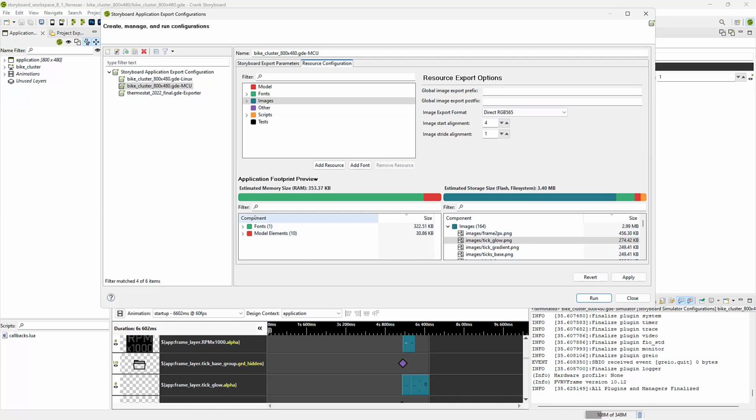Now you'll notice a difference in the sizes. At design time, we've pre-processed that file. We've inflated it. We've laid it out in a way that is compatible with the target board and the GPU, such that it can be blitted or direct copied from flash directly to the frame buffer. In this way, we remove the intermediate buffers, and you can see the RAM sizes drop significantly. We also remove the CPU cycles of inflation. So it's a very efficient way of doing things, and the ARM2D library does this for us.